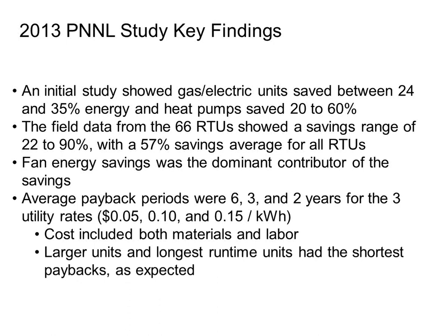The more CFM I'm running through the unit, the faster my savings could be. The control widgets basically cost the same whether I put them on a 5-ton unit or a 50-ton unit. Sure, the VFD gets a little larger, but the sensors and all that stuff, actuators, it's all the same. So the bigger the unit, the faster the payback's going to be, right?